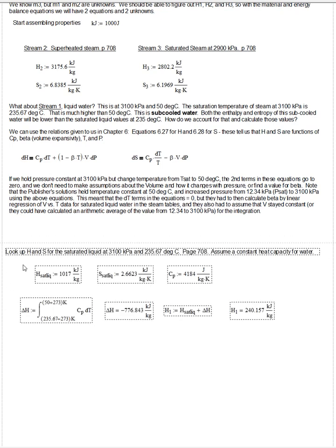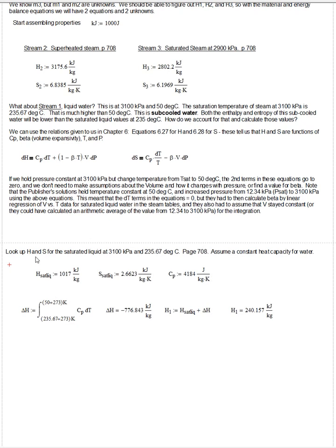So what I've done here is I've just tabulated, I've just put down, the enthalpy of saturated liquid at 3100 kilopascals, 235. I also wrote down the entropy of saturated liquid, because we're going to have to do that calculation as well. And then what I did is I looked up the heat capacity of water.